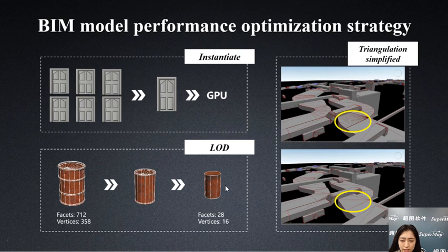LOD technology is the abbreviation of levels of detail, which means multiple levels of detail. So LOD technology refers to determining the resource allocation of object rendering according to the position and importance of the node of the object model in the display environment, and reducing the number of faces, surfaces, and details of non-important objects, so as to obtain efficient rendering operation.